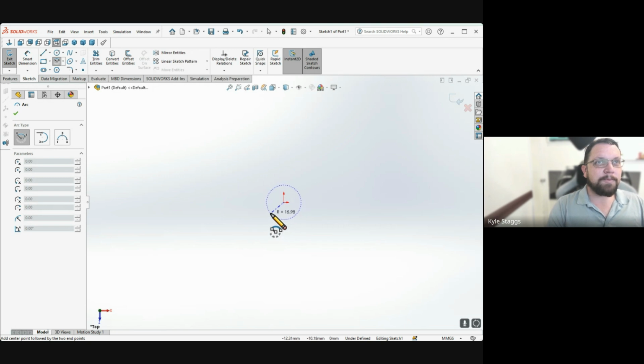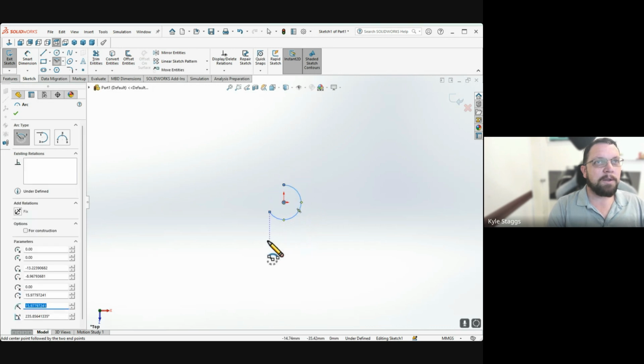For the French curve, you've got some starting point, and you've got an ending point for each arc. There's going to be a lot of these 3-point arcs. So you start by selecting the center point, then you select one point where the arc starts, then another point. Then there can be a few others that will show up.